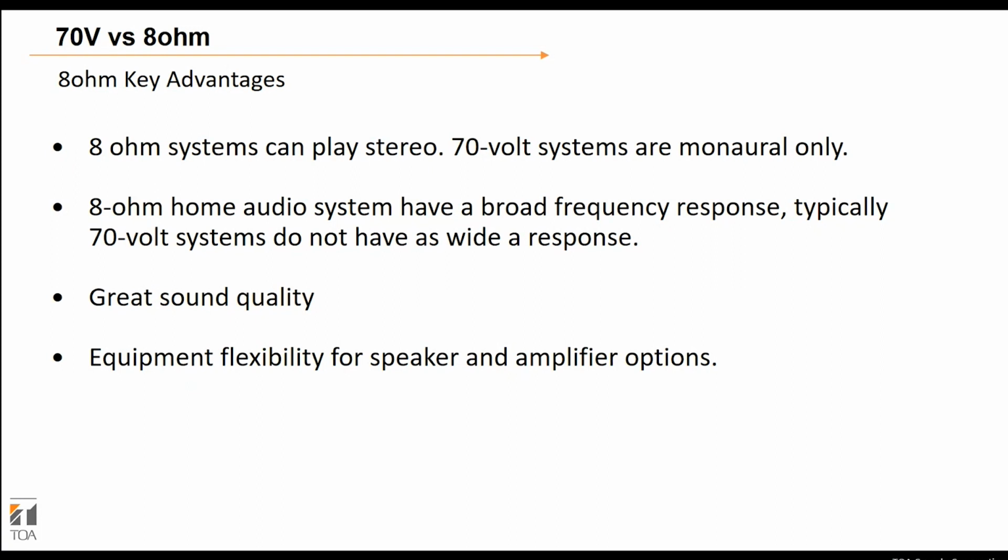So an 8 ohm home audio system would have a broad frequency response. Similarly with pro audio, you're going to have a very broad frequency response and cover all of the different frequencies that speaker is capable of reproducing. Whereas typically a 70 volt system does not have quite as wide of a frequency response. And that's typically a characteristic of the transformer that's being used on that system.